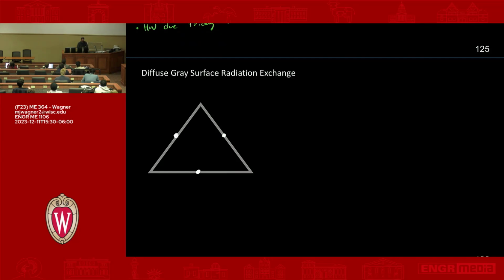And in each of these nodes, there are maybe some things that we can model or consider. So before, we said let's say we have some heat transfer Q dot across this node 1. Let's assume that this surface 1 is a black surface. Let's assume surface 3 here, this emissivity 3, is equal to 1 as well. So we have two black surfaces.